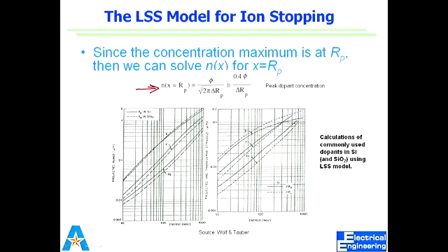So if you know this, then whatever your mask is, the thickness of the mask will define how many ions pass through. At each thickness of your mask, whether thinner or thicker, how many make it through, and what these two would be, will be different at different points, right? How much energy they have while they get into silicon will define what point you have to use based on the energy.